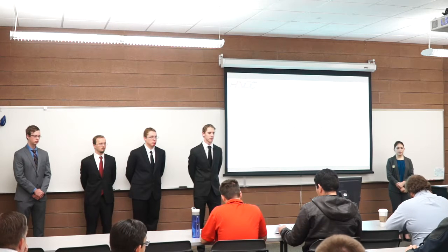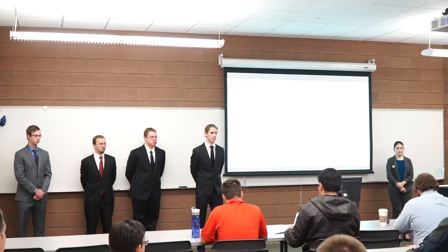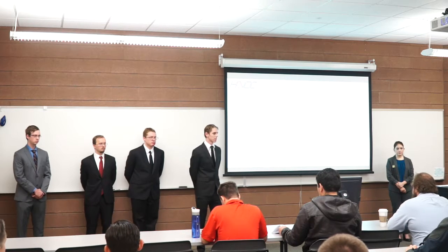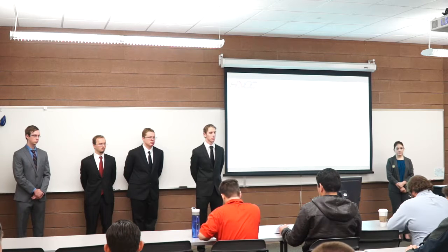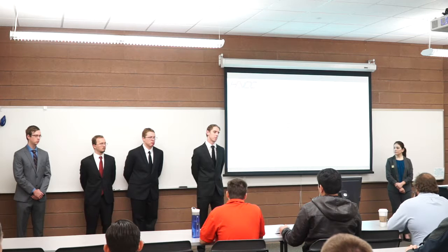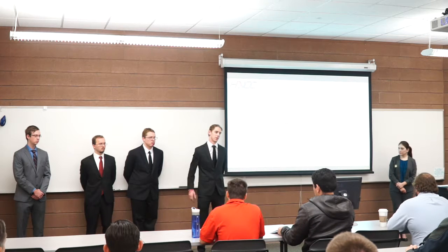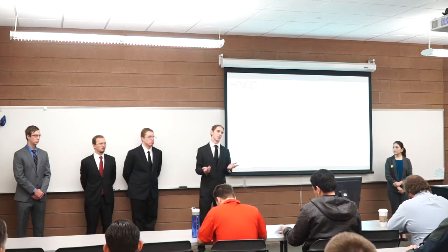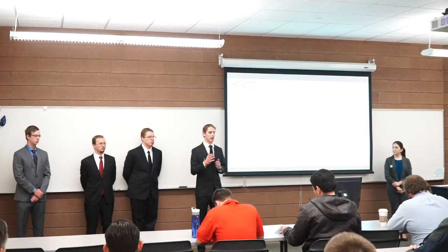That's a critical aspect of the design, and I would say that should be included in a design review because that's something you want feedback on. Okay. The second part of that question was, how many tendons per servo? So there's going to be 1 tendon per servo, but in order to actuate, sorry, I guess it's technically 2 tendons per servo because we're trying to actuate the link in both directions.